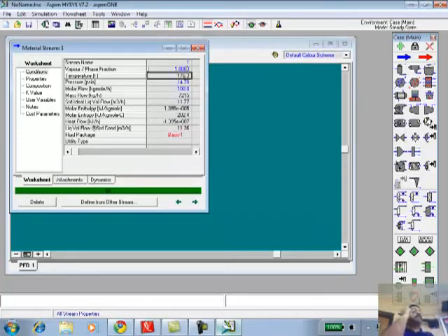Did it feel like the value stream? Very good question. So how did it get the K value? Can we get access to the K values? And will the K values change as I change the temperature and the pressure? Obviously, it will change. It makes a call to the Peng-Robinson package and says, this is my feed, these are my temperatures and pressures, you calculate the K values and send them to me. Then I can solve this particular problem.